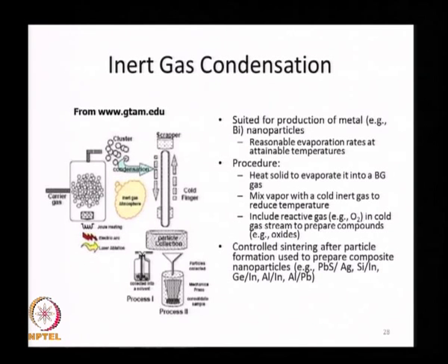So, this is essentially a two-stage process where you first do a low temperature process to make nanoparticles that have essentially a loose structure, and then you do a high temperature sintering to provide a more specified composition and structure by introducing multiple precursors into the reacting mixture.